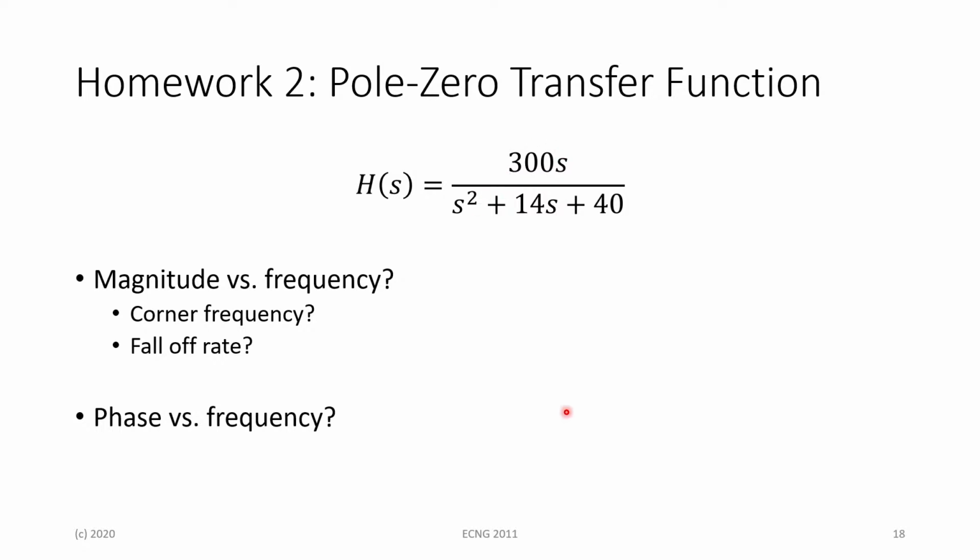The phase plot is basically going to be unaffected because constants basically don't contribute to anything towards an angle throughout the entire plot. And because this is a positive constant, and we saw in yesterday's lecture for anything that's a positive constant, the phase is just going to be 0 degrees.